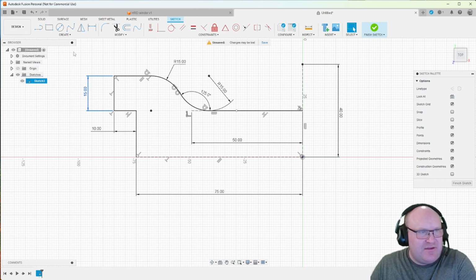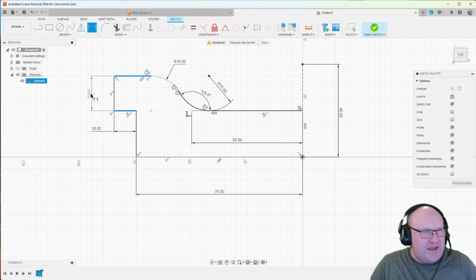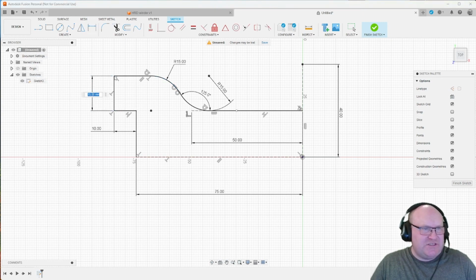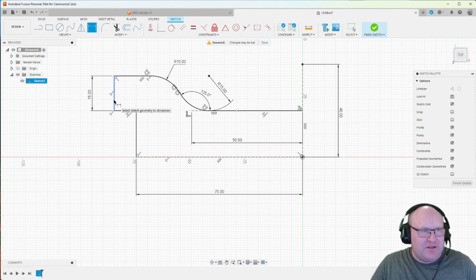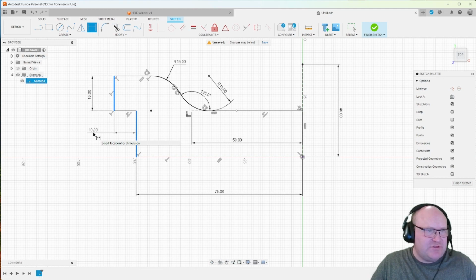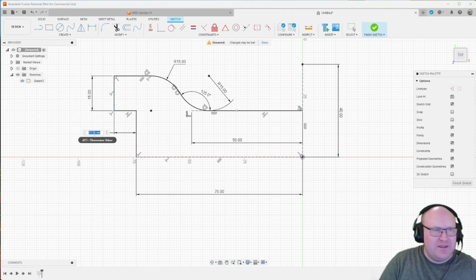So just select it, click here, click sketch dimension, and click this line to this line. And that is the dimension we would like to keep, not the one which is the point to the point, because we are going to remove the point. Same here, delete this dimension, click here, and then place this wherever you want, and then you have your dimension.